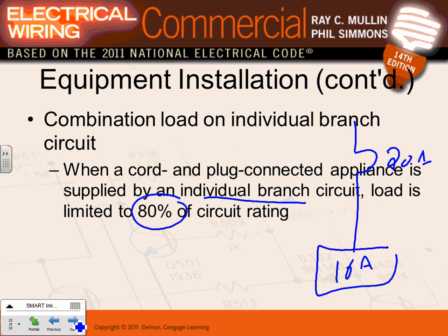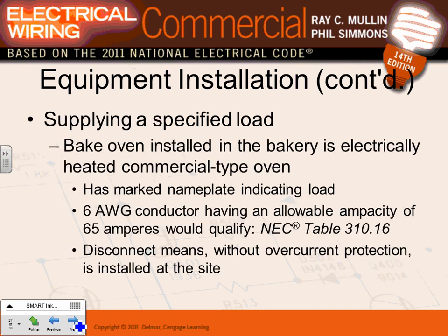I can't feed 20 amps. Right? It has to be 80% of the rating. Can I have a thumbs up, Chad? That's how we size everything with me, guys. When you were multiplying by 1.25, that's exactly what you were taking into consideration, the 80%. Okay.